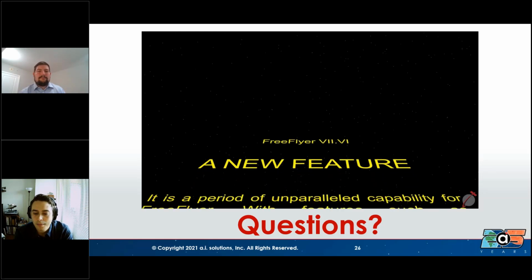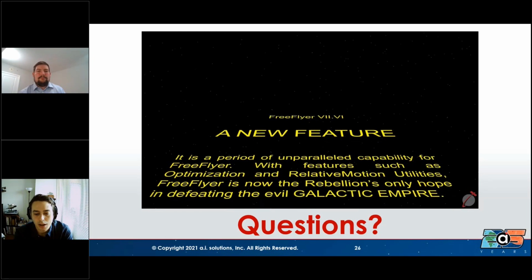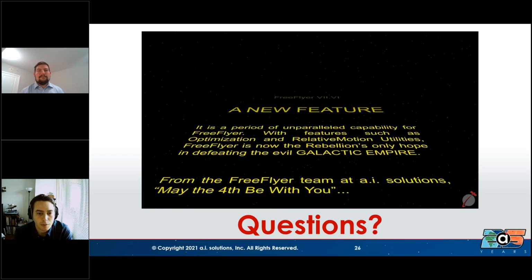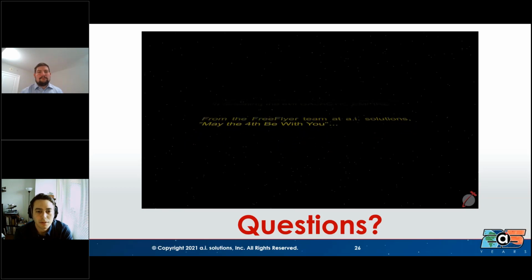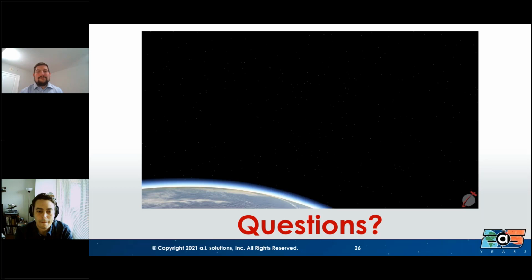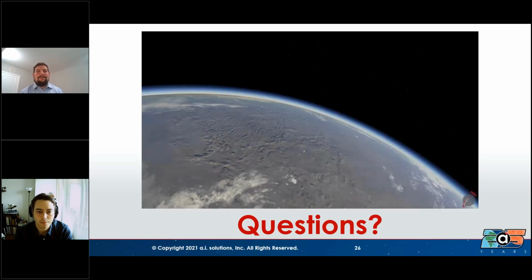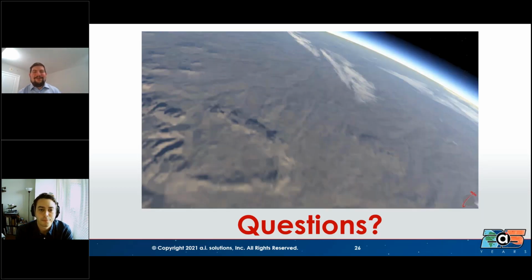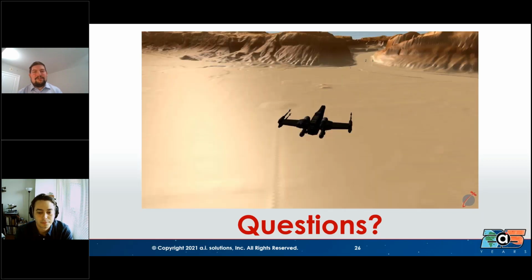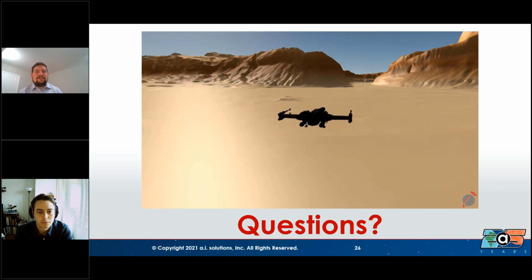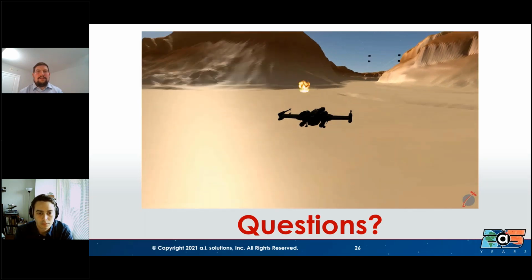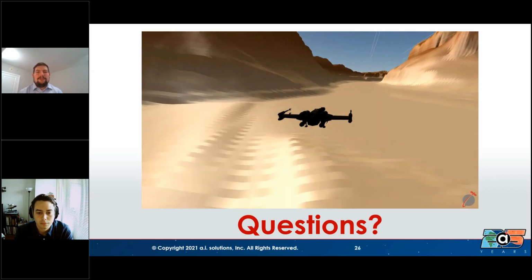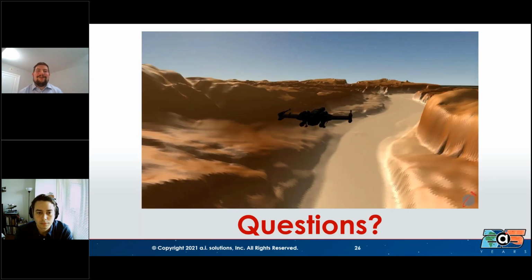Okay. Next question is, you mentioned the output of data, the reports, plots, and everything. How can you output your visualizations, or can you? Oh, so I was showing them on the screen, but how can you output them to other people? Good question. So you can save an image from any portion or the whole thing of FreeFlyer, and you can do that from script so that you don't have to be there to click the save image button.